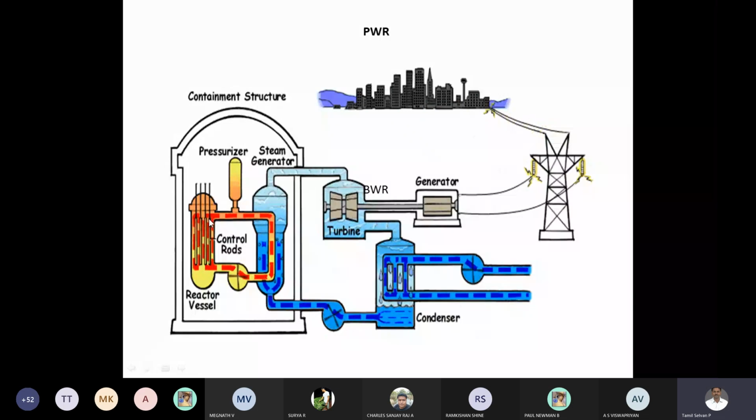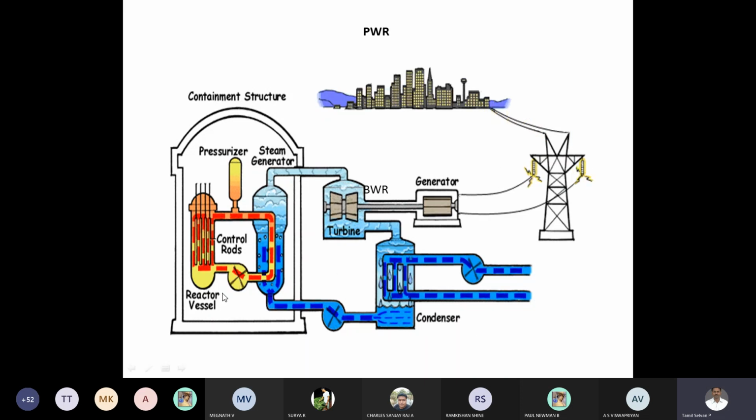So now what happens here is, from the hot reactor core, the coolant, liquid sodium, takes the heat energy and passes through the tube, and it transfers the heat energy to the tube material. So that's why the tube material should have higher thermal conductivity, so that it can transfer the heat to the circulating water, so that the water gets converted into steam. And the steam runs the turbine. We know that we get the energy. So our concept is the heat transfer by means of convection.